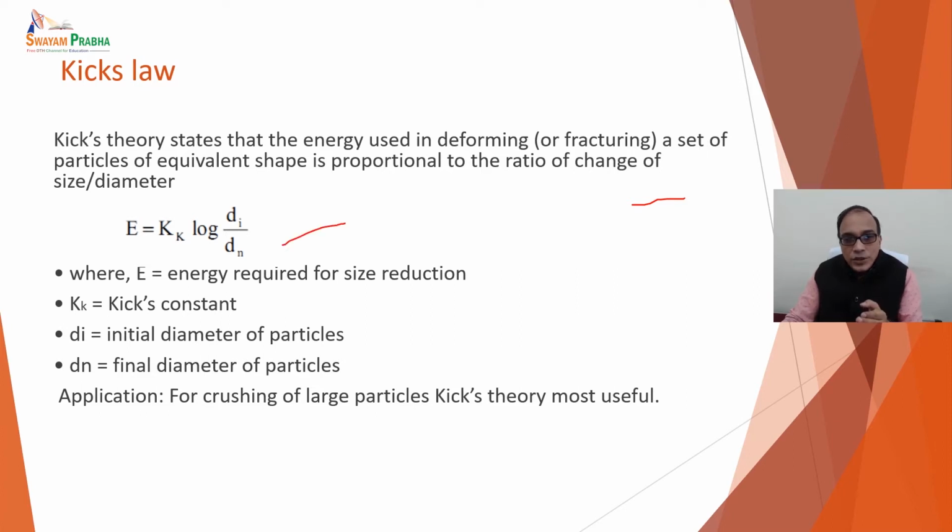This is the equation you can see, where E is the energy required for size reduction, K_K is the Kick's constant, Di is the initial diameter of particles, Dn is the final diameter of particles. You can use this law for crushing of large particles. So for this particular area, Kick's theory is most applicable.